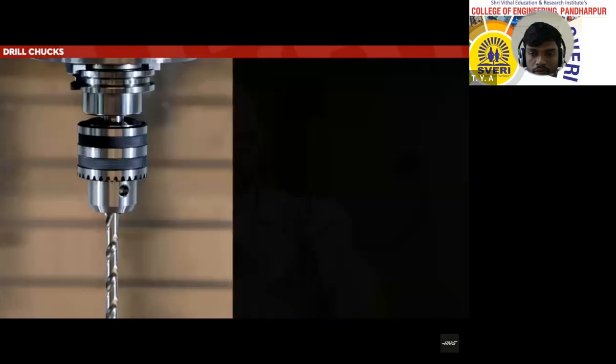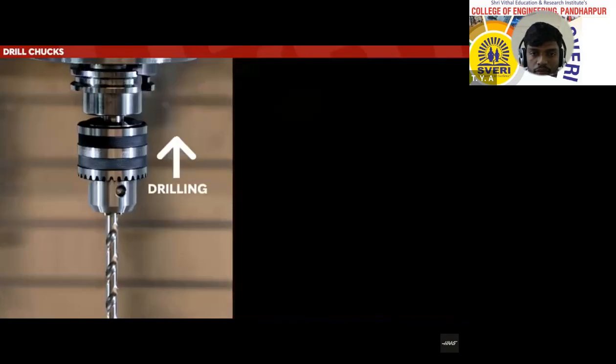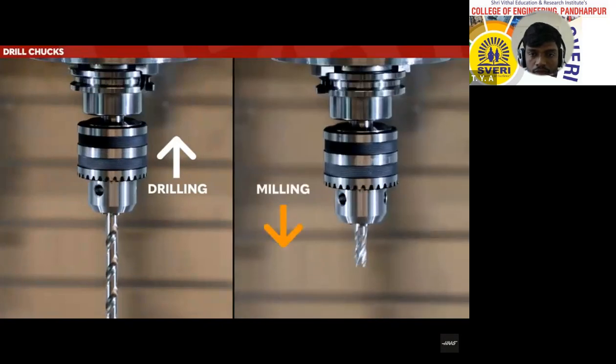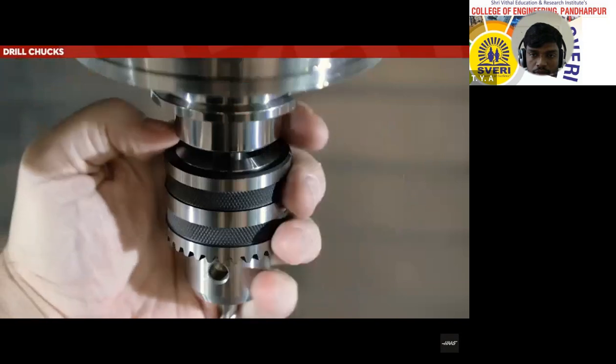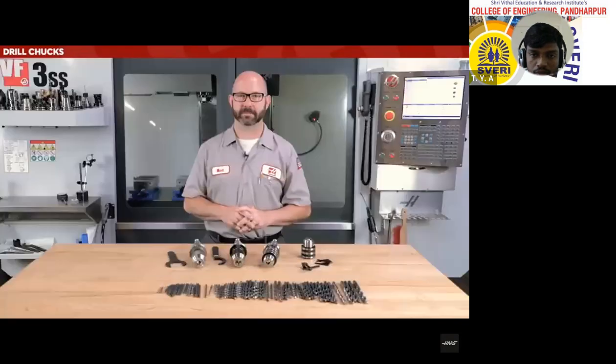Now, while drilling, these two pieces are being forced together at all times. The drill is pushing up axially and forcing these together. With end mills, the exact opposite is happening. It's trying to pull that tool out because of the helix on the end mill, and it's going to want to separate these two. And nothing good can happen. You're not getting extra grip by any means.